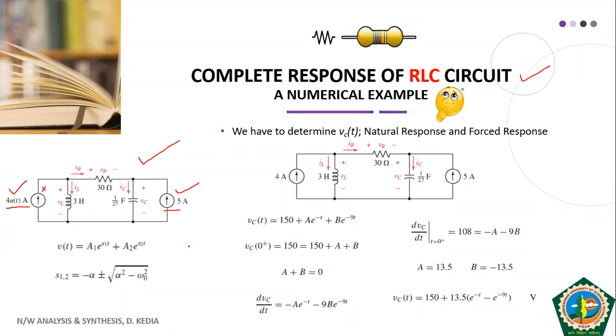Okay. So dear students, as I told you, first we need to look into whether our circuit is a series RLC circuit or a parallel RLC circuit. So just ignore the sources which are present. You open circuit this current source also, and you can see that these R, L, C are in a series RLC circuit. Okay. So since we have obtained a series RLC circuit, the next step is to find out the value of alpha and the value of omega naught.